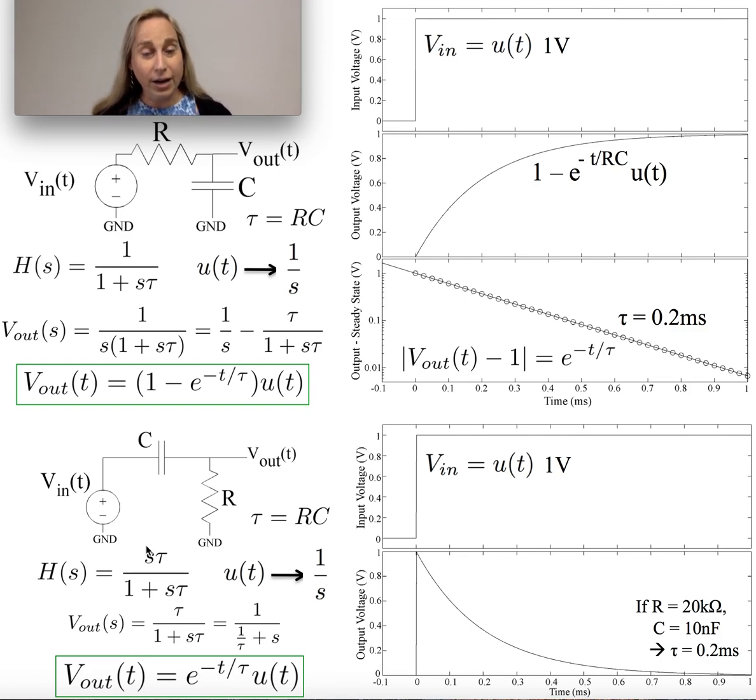And you want to think, well, how do I begin to analyze that? Well, the big way we typically measure these things is with step responses. One of the reasons is that experimentally it's really easy to do a step response because you usually apply some sort of square wave to the input and you can build from there. Okay, so a typical step response is going to be 1 over s in the Laplace domain, and I would get that in both cases.